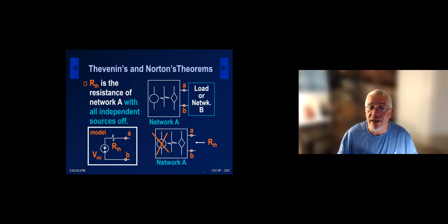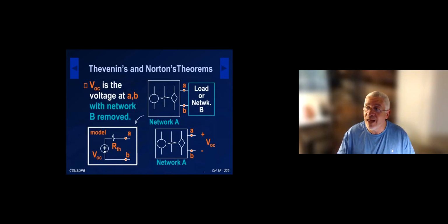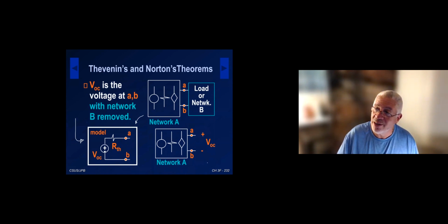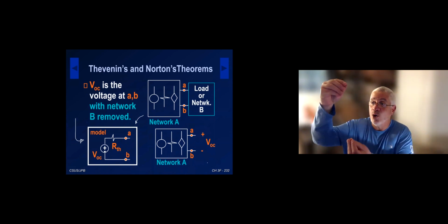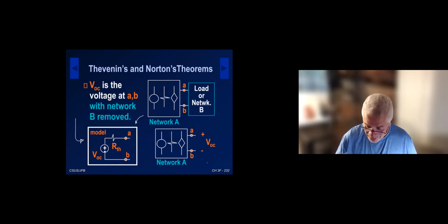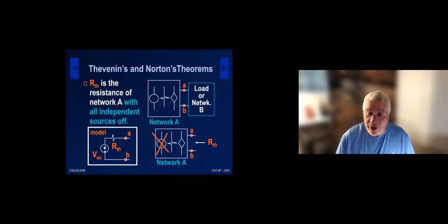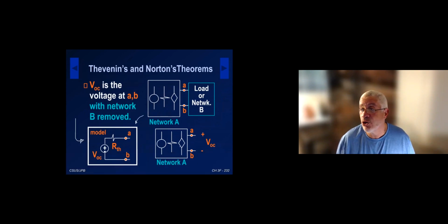So these are the two steps into the Thevenin model. First, we have to come up with the model. That's right here. You have to show me you know what the model is. Then you proceed to calculate VOC from the given circuit, which is essentially the open circuit voltage across the circuit you want to model. When we calculate VOC, nothing is turned off.